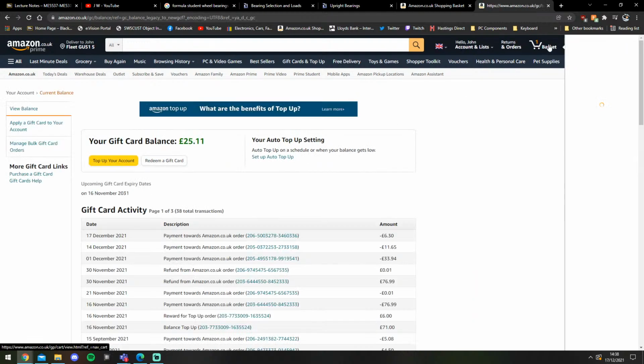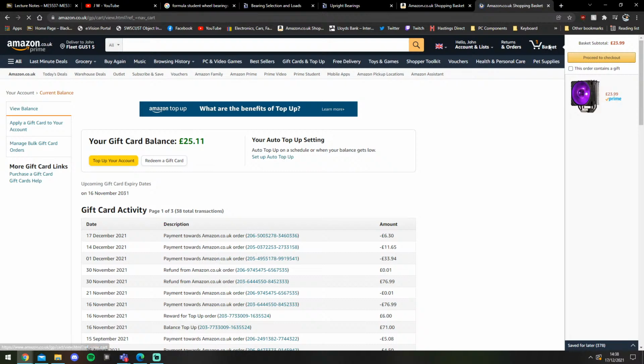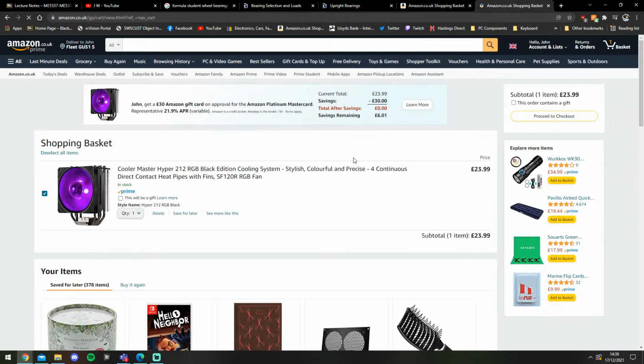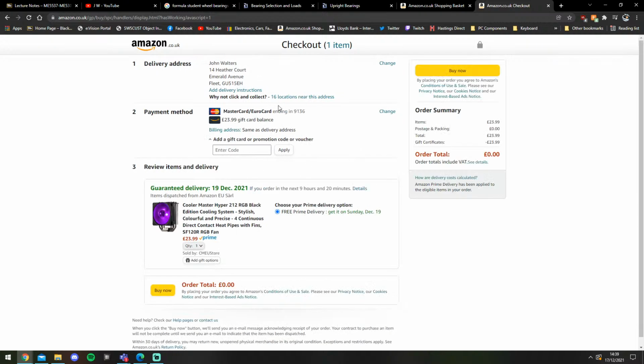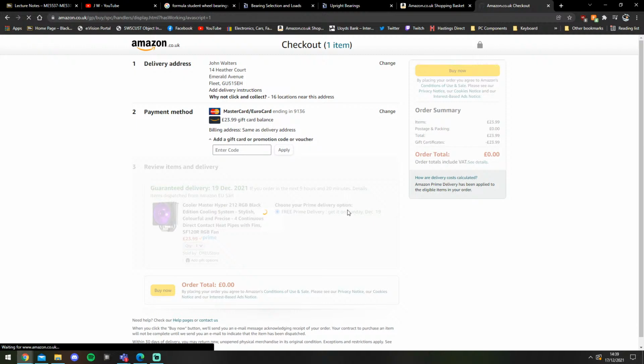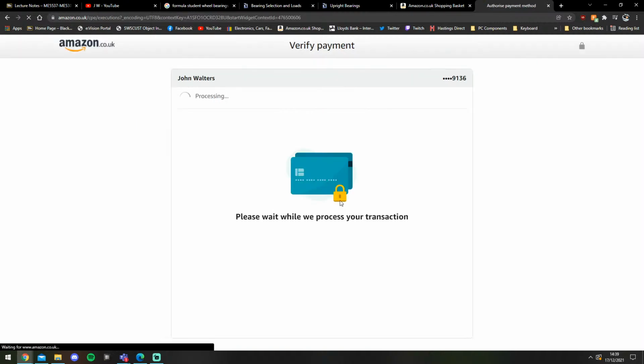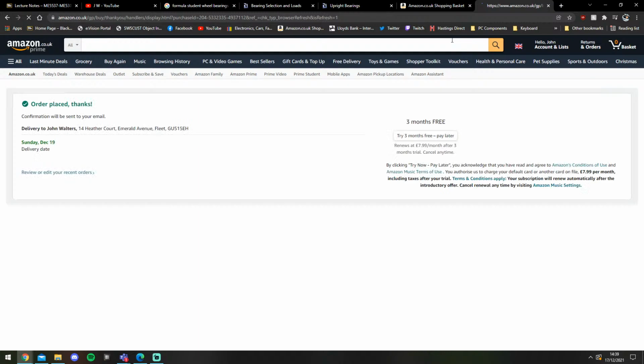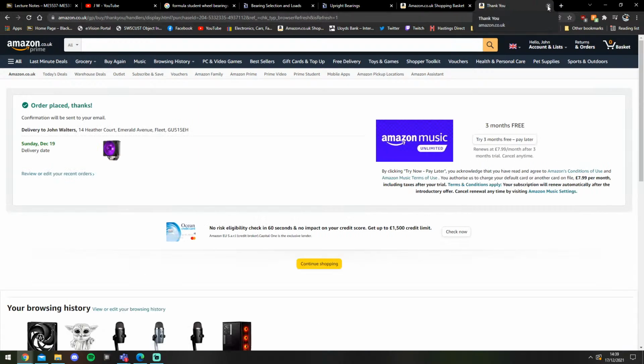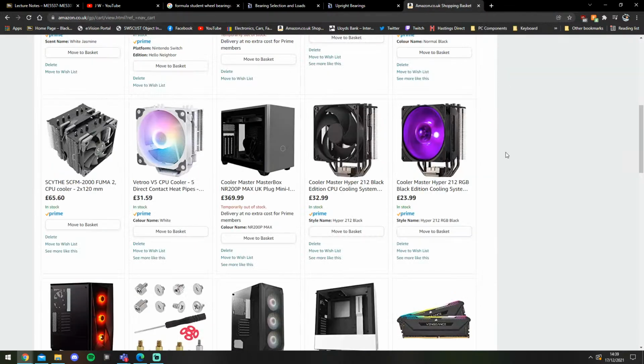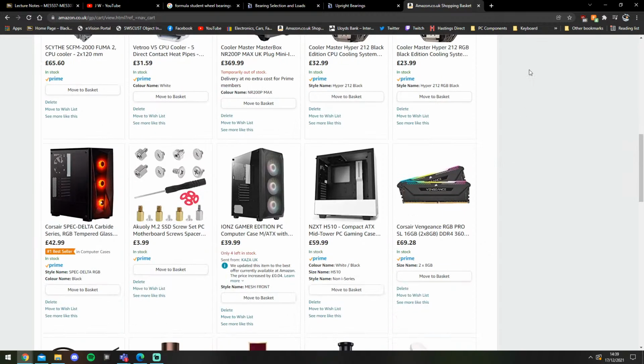Okay, some minutes ago I was asking which one is better for the particular case shown in the performance map of the radiator: to increase the coolant flow or the airflow. The answer was that for the particular case, the increase of the airflow is much more effective. And then the question was how to achieve that.